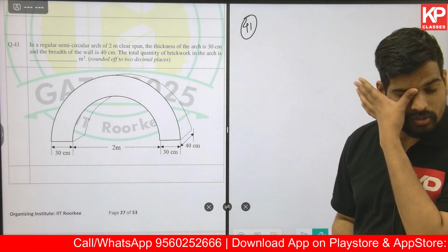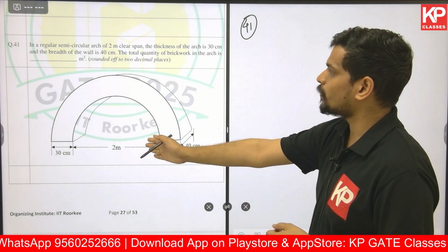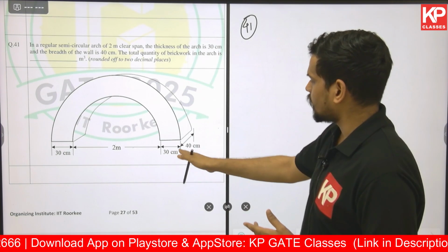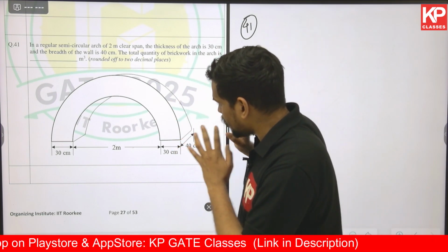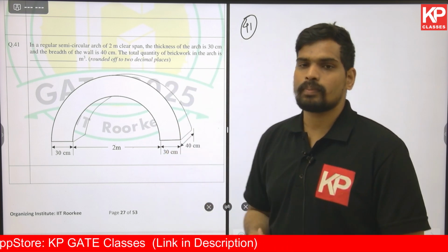A simple question based on estimating the quantity of a semicircular arch. In a regular semicircular arch of 2-meter clear span, diagram also is given for us, 2-meter clear span. The thickness of the arch is 30 centimeters as shown in this diagram. The breadth of the wall, the thickness of the wall, or basically the depth of the arch, that is 40 centimeters. The total quantity of brickwork in the arch in cubic meters is being asked.